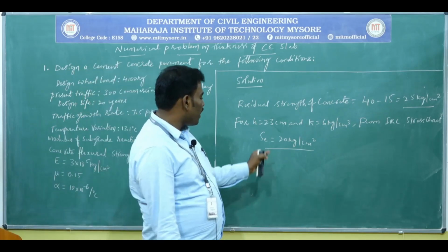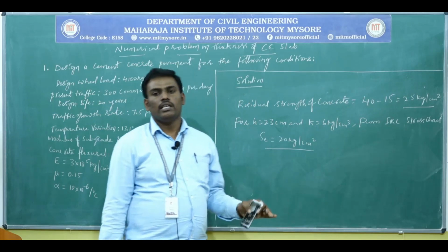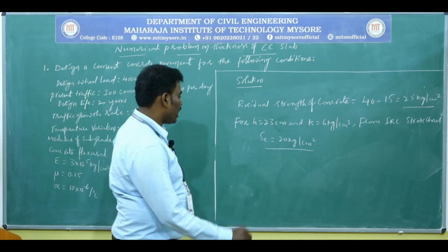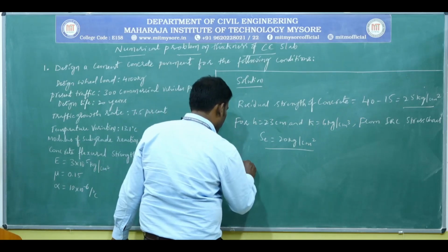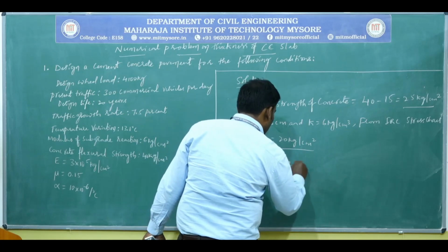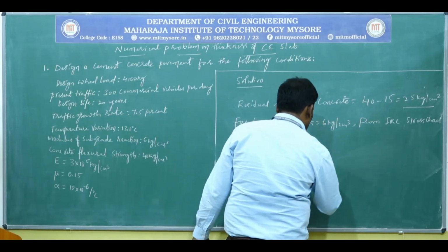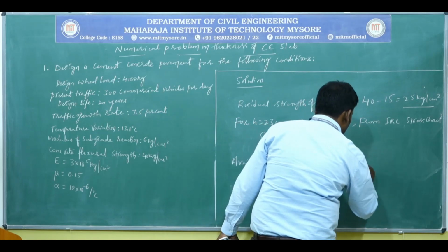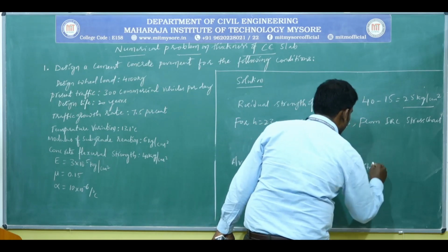Once you have the wheel load stress, you need to check the available factor of safety on load stress, that is the wheel load stress at the edge region.